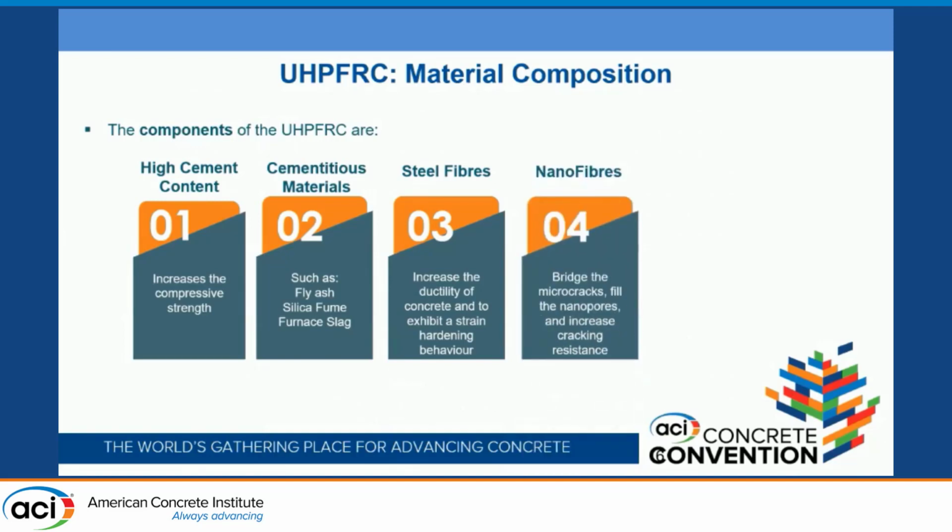The nanofibers, some UHP FRC has nanofibers in order to enhance or increase the cracking resistance of the UHP FRC, because the steel fibers are not efficient in bridging the micro cracks, and that's why the nanofibers were introduced to do this instead of the steel fibers.